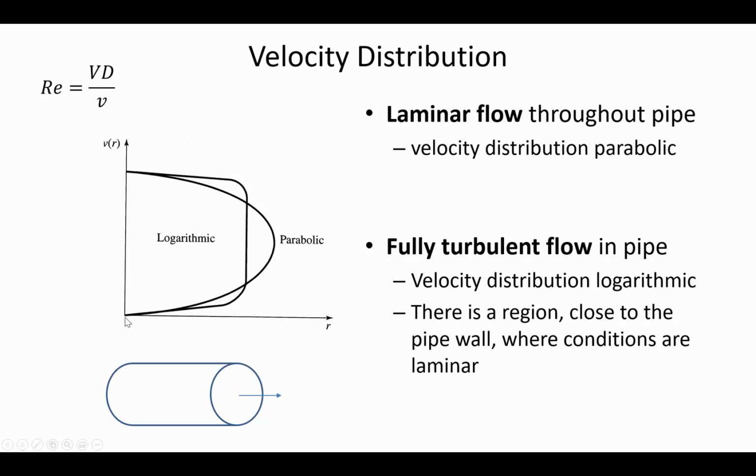And so what's being represented here is the bottom edge of the pipe, here's the top edge of the pipe, and so what we're saying is as you get close to that top boundary or the bottom boundary, that the velocity is dropping essentially down to zero. And that no slip condition says that the water that's in contact with the pipe is moving at the same velocity as the pipe, meaning it's not moving at all, as zero velocity. The water that's right in contact just at kind of the molecular level is held at zero velocity.